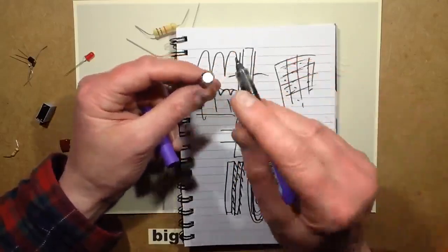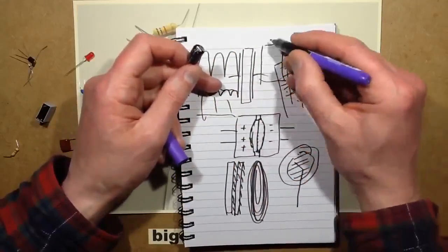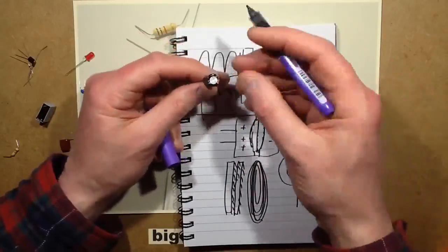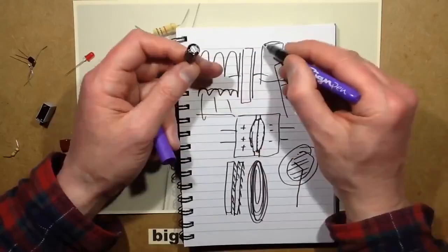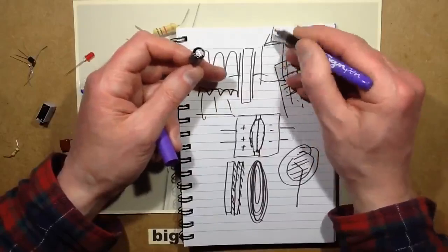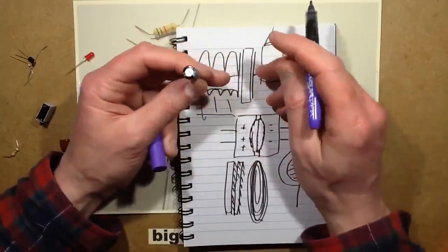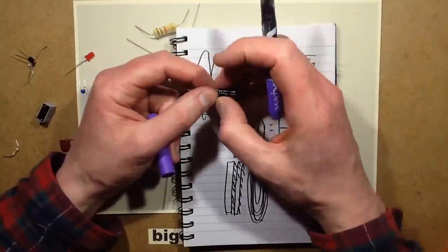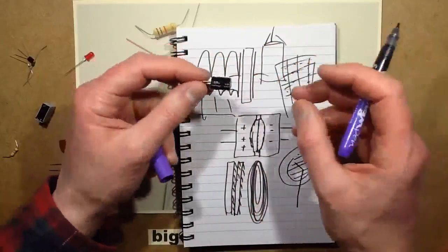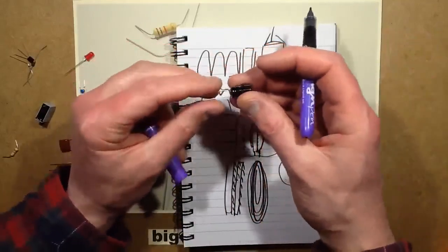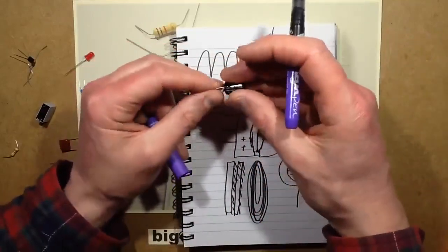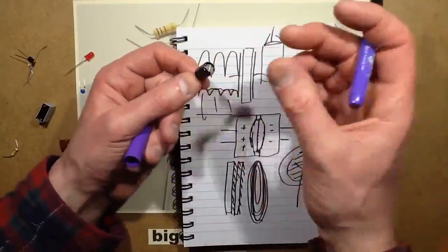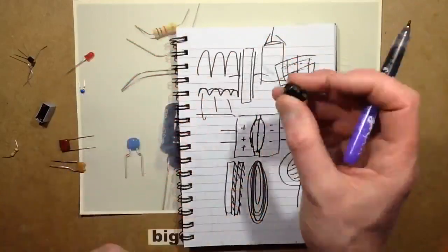And when that happens, if you looked at it from the side, the top would bulge up. But if it goes too far, that X that's etched onto the top will split open and it will vent out the top. And the other option there, if it doesn't do that, is sometimes it blows the whole can off and it just makes a mess. It gives out a vapour of the electrolyte, which is slightly caustic. It can unravel the foil across the room. It can go off with enough force to actually cause injury if it hits you. So you have to be kind of careful with electrolytic capacitors.